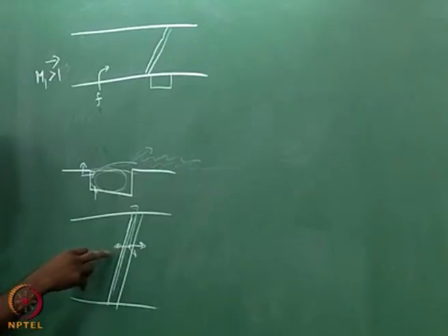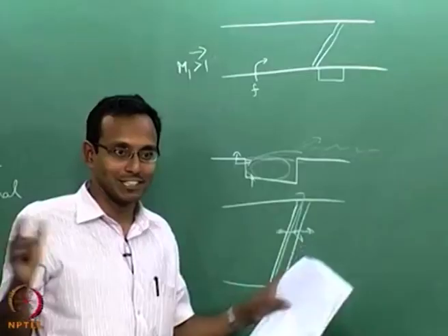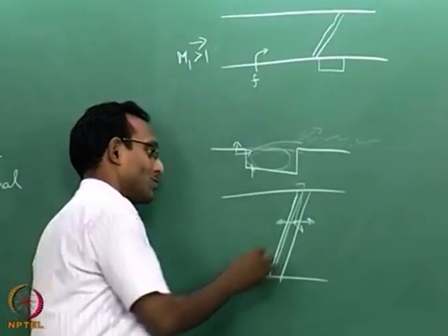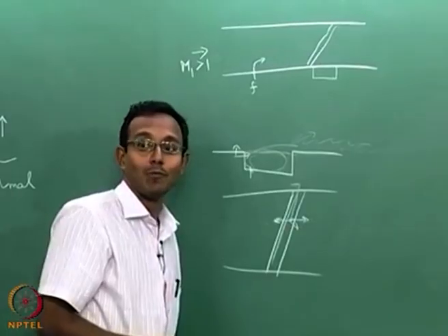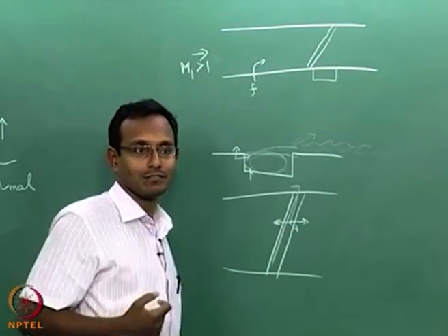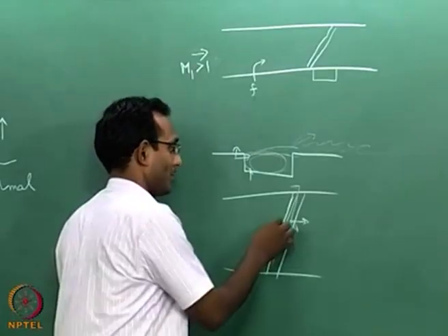So they have to think about perpendicular injection or against the flow injection typically. When I do that, I am fighting the flow if I inject against it, so the P naught loss will be a little higher, okay. I am trying to link all the things that you have learnt in gas dynamics till now in this one application. So I am resisting the flow more, so the energy of the flow will be lost more, P naught will be lost more.